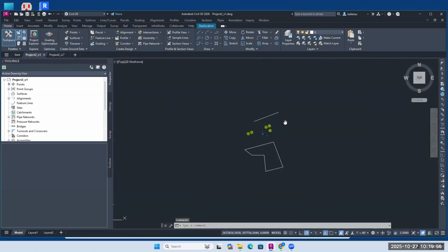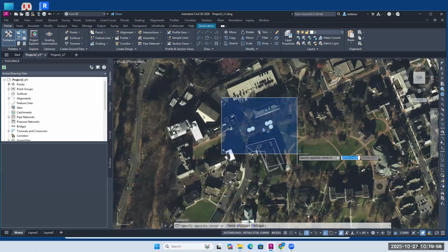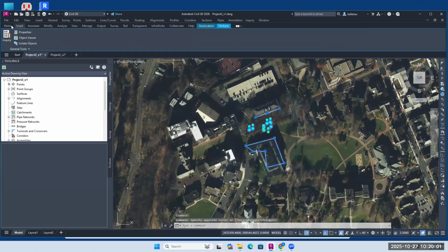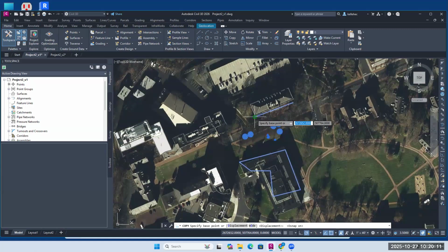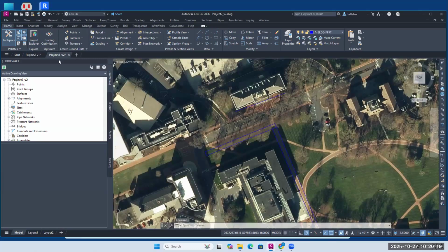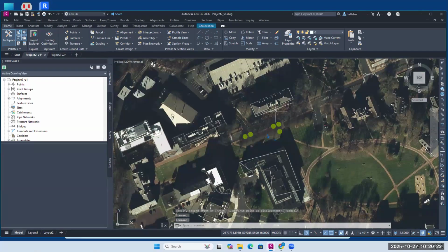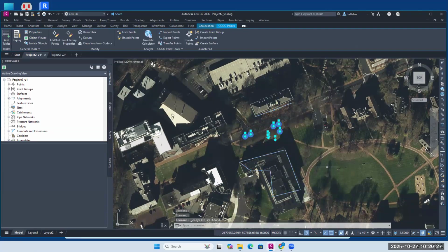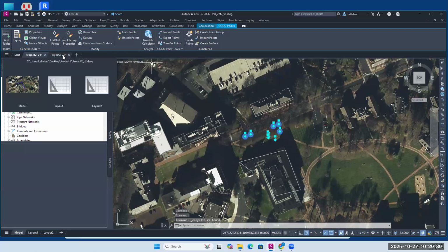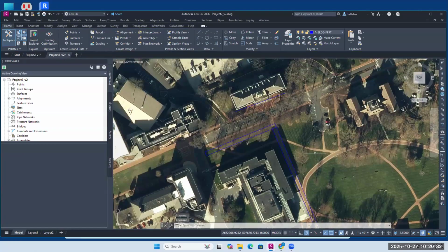So if I go to this drawing, what I'm going to do is grab everything I want to copy. And I am actually going to go up here and say copy, and specify a base point. I'm going to turn on this snap and click this edge. And if you do this, you get this weird situation where you can't move it in. So we can't use that functionality. Instead, what we're going to do is select everything and say Control C. And this puts it in a place where we can now move it between drawings.